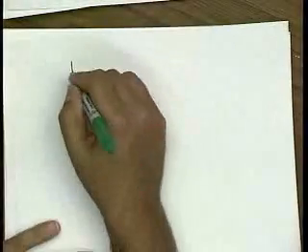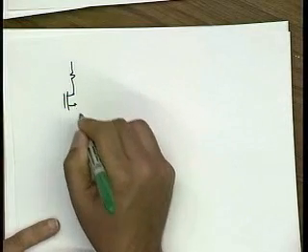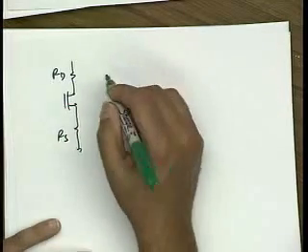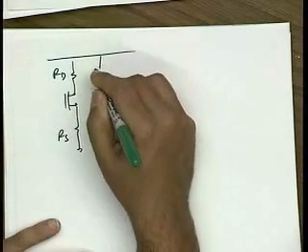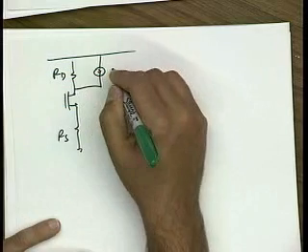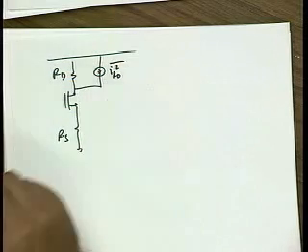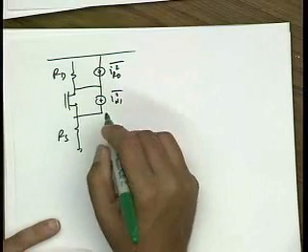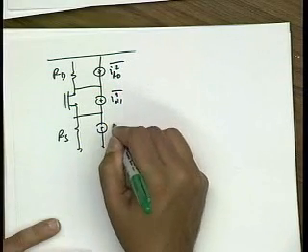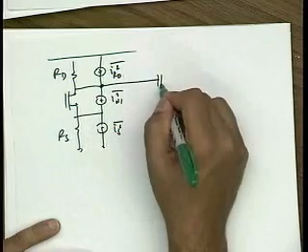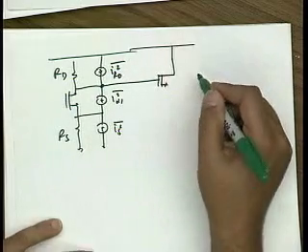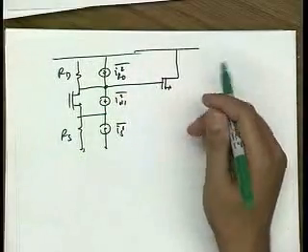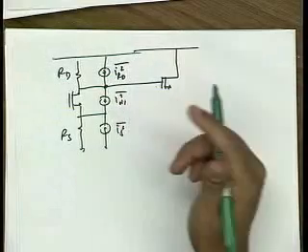Okay, so let's come back to our problem and finish it off, finally. This problem, I think, if you want to do it right, is too long. So what I was really looking for on the midterm was a very quick and dirty approximation, which I'll tell you guys what it would be if I had to make it. Somebody held a gun to my head and said, what's the noise? You've got 10 seconds. I would say it's the noise of the common gate. Second stage is not going to contribute noise. So I would say it's 1 plus gamma over alpha. Okay.